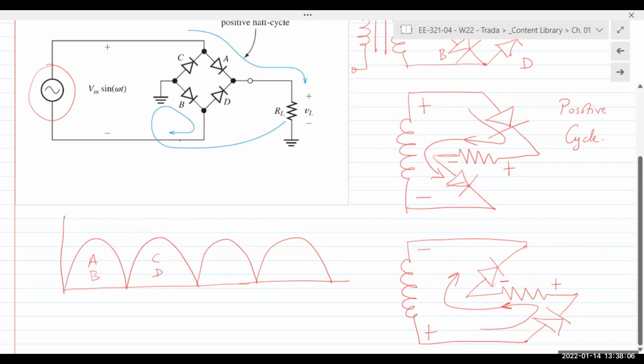So anytime in a circuit, most circuits will have hundreds and thousands of components. So to mark the same spot in a circuit, they will have the same symbol. Meaning if there's point B in a circuit, and there are multiple components connected to point B, but in the circuit schematic, there might be like 3, 4 different components all spread far away. So in a schematic, we might just mark everything as this is point B, point B, point B, point B. So if you're reading a schematic, you would take it to mean that all of those are connected together.